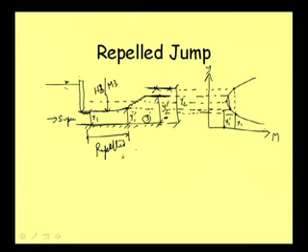Okay. So this is one type of jump, and that is why the tailwater depth here is important. Suppose we have a low tailwater depth, then this water is emerging with high energy, and to meet the low tailwater depth, this water will be moving in the downward direction as supercritical flow, that is, with high energy. Then there is a longer portion that is subjected to high energy or high velocity flow, which can cause damage to the bed.